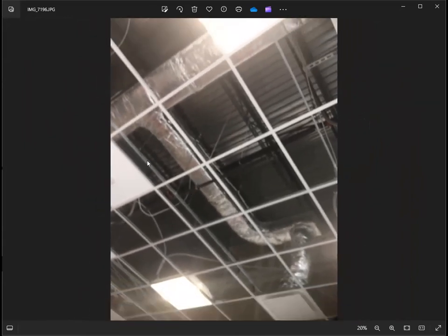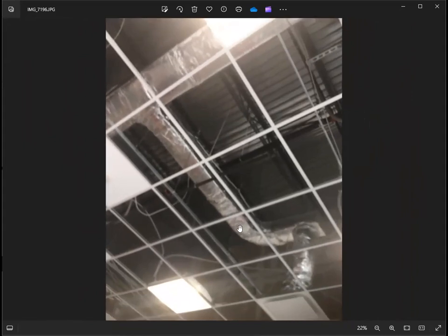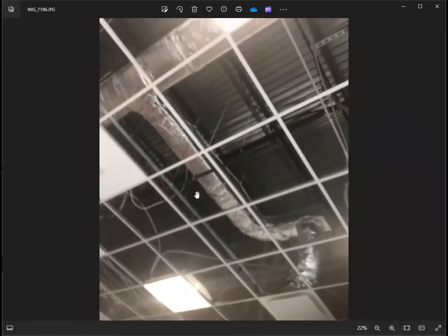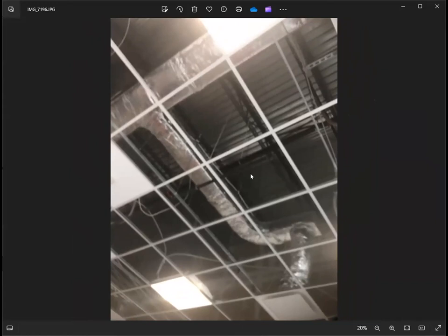Supports should be spaced acceptably as per code and as per drawing details. More likely, every turn should be supported, and hanger support should be at least 6 to 10 feet apart, depending on the condition of the job. And you see light fixtures are installed also. Under the energy code drawing, I have a reference that I will show you in the slides and the photos that I've taken.